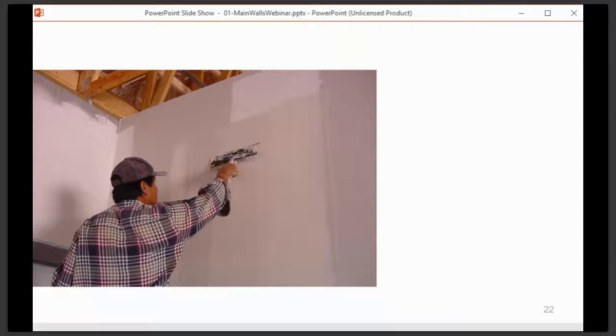If you look at some of the DIY manuals and some of the things online, they'll say that you don't necessarily have to do that. If you apply the joint tape and you cover the joints correctly, it's not necessary. But I would always do a skim coat of plaster over. It just gives a perfectly smooth finish, and also it's a much better finish for other applications to adhere to. Plasterboard is actually covered in a very thick paper, for want of a better description. If you apply, say, a wallpaper to that, when you go to pull that wallpaper off in the future, it could actually damage some of the plasterboard by peeling that away. So I would always make sure that I have a skim plaster finish. It gives it extra strength, and it gives you more flexibility in the future as well.